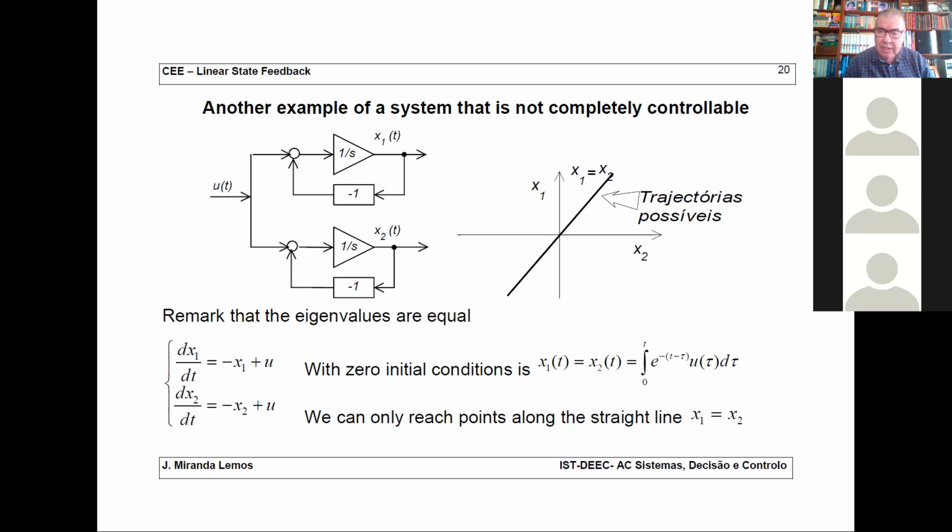And also you can think, I want to do it with the least possible energy. That is still another problem. But in a word, to answer your question, controllability is related to the position of your actuators. If your actuators are not in the correct position, then the system will not be controllable.